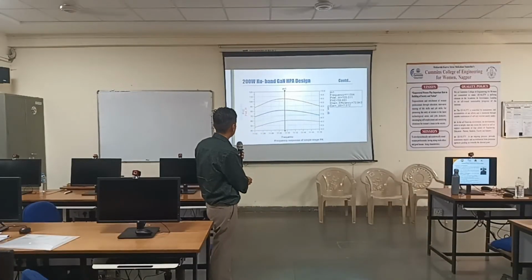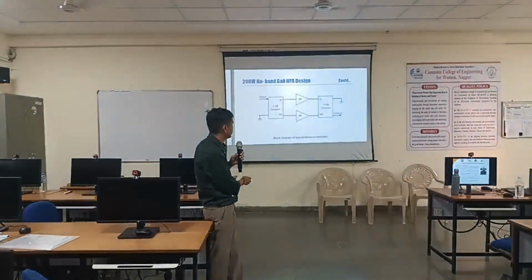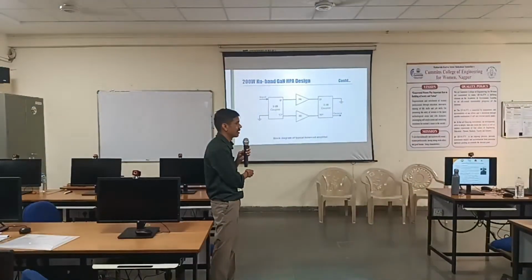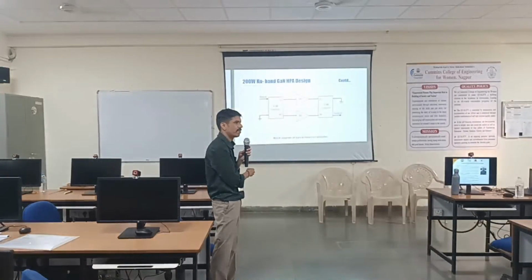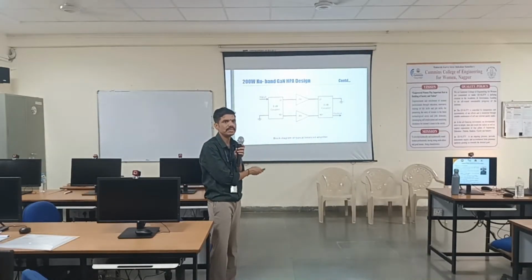Let me go to the double stage. Yeah, I did this. So PA1, PA2, I cascaded both in parallel. One coupler at the input, one coupler at the output. Coupler you can use as a divider or combiner. Same coupler I can use at input and output.